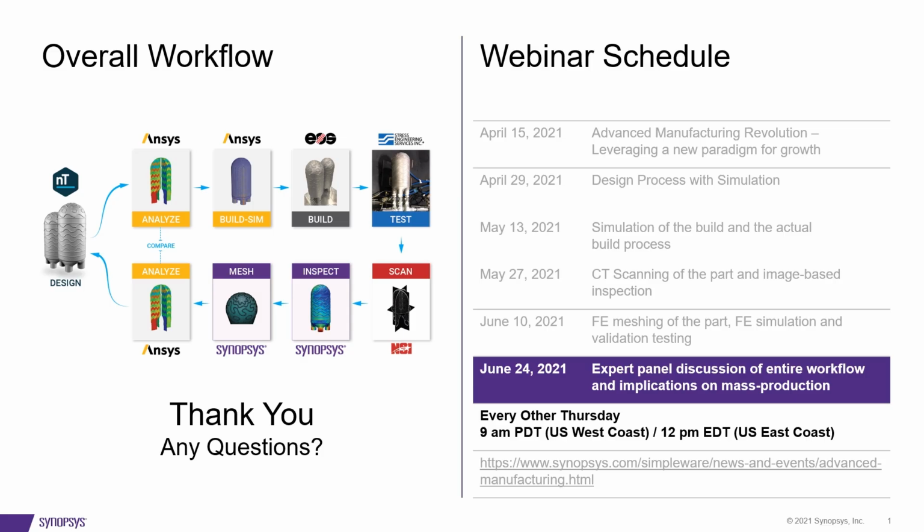I would say there are a couple of things the analysis maybe needs. There might be a slight change in approach if we want to match the analysis to the DIC correlation completely. We've seen from our existing results, just looking at it from 10,000 feet, that it has a lot of similarities in terms of where the hot spots are, and also the order of magnitude of the strain. So that part we are pretty comfortable that they match.